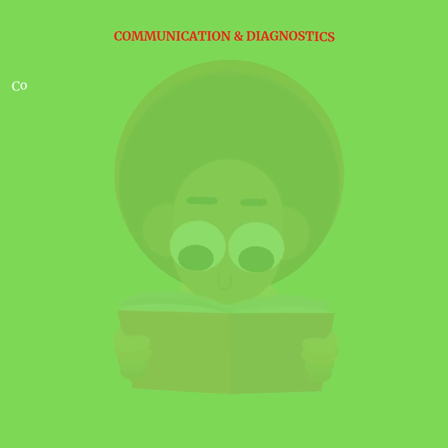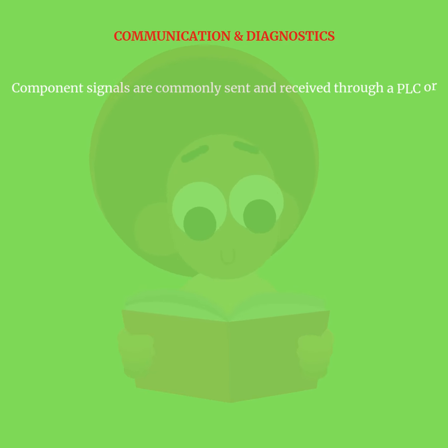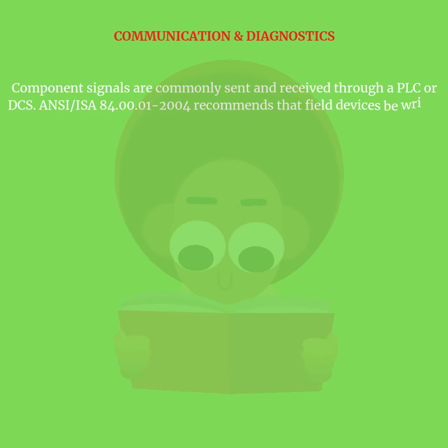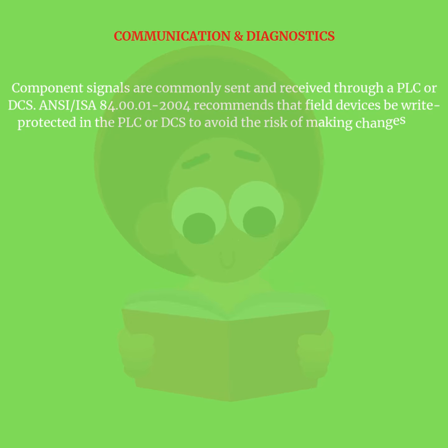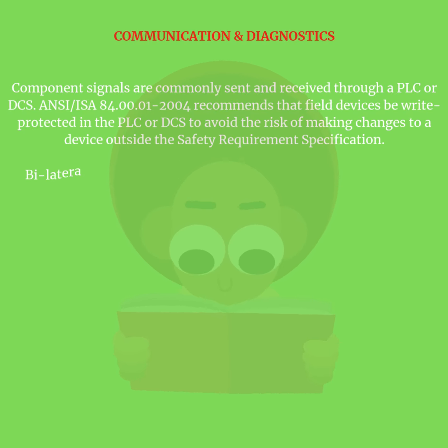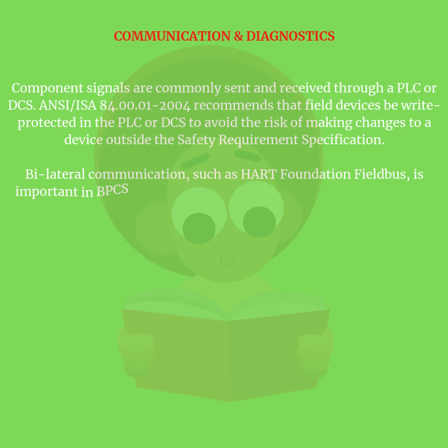Communication and diagnostics. Component signals are commonly sent and received through a PLC or DCS. ANSI/ISA 84.00.01-2004 recommends that field devices be write protected in the PLC or DCS to avoid the risk of making changes to a device outside the safety requirement specification.